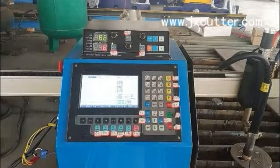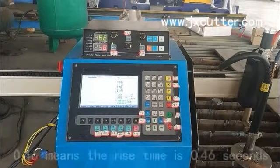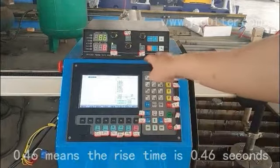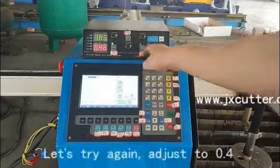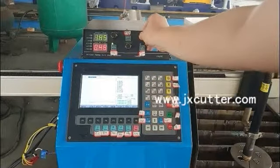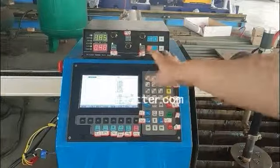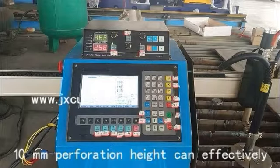Let's see if it is larger than 10 mm. We will adjust this position smaller. 0.46 means the rising time is 0.46 seconds. Let's try again. Adjust to 0.4. The height is about 10 mm. A 10 mm perforation height can effectively solve the nozzle burnout problem.